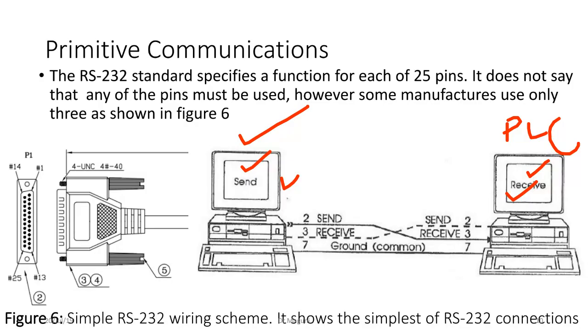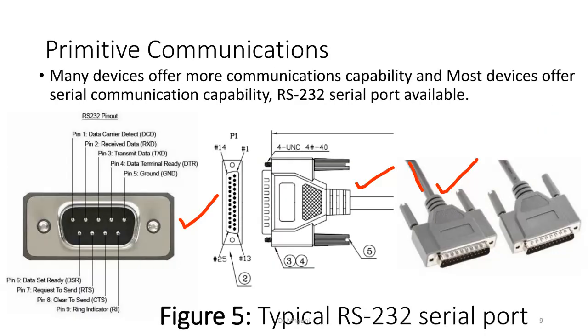This is where they introduced what we call handshaking. Now, what does the handshaking operation imply? The first computer tells the second computer that I have a message that I would like to transmit. And then what will happen? It will acknowledge that information. But how do you accommodate that? That is where you introduce the fourth pin. Let's go back to our case here. Now, we used pin 1.